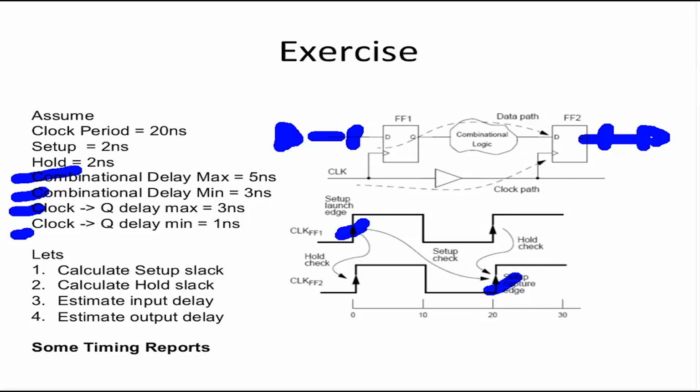So delay is calculated and then checked against the timing constraints. What are timing constraints? There are two types: max delay constraint and min delay constraint. Max delay constraints are usually checked in the worst case corner, I mean, the worst case corner is critical for max delay constraints. Max delay constraints are of the setup constraint type. Min delay constraints are critical at the best case corner, and min delay checks are also called hold checks.